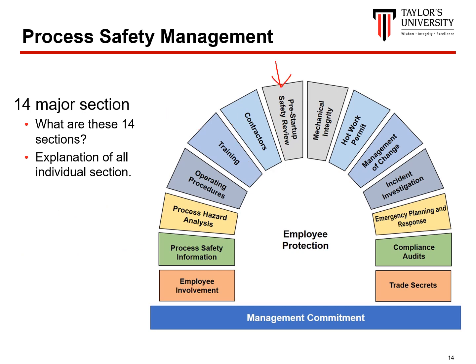A pre-startup safety review is a special safety review that is conducted after a modification to the process or after operating conditions have been changed, and before the startup. In this review, a team of reviewers has to ensure that first, the system is constructed in accordance with the design specification. Second, the safety, maintenance, operating, and emergency procedures are in place. And third, the appropriate training is completed. And fourth, the recommendations from the PHA are implemented or resolved.